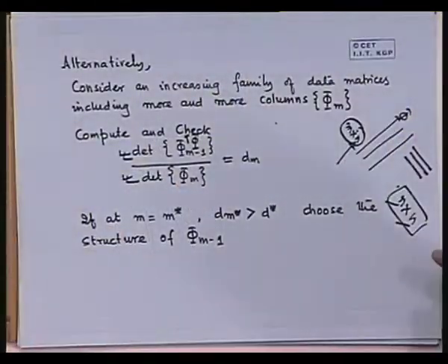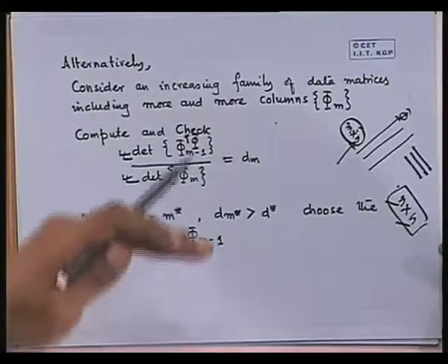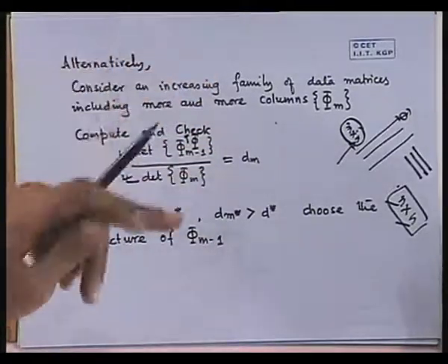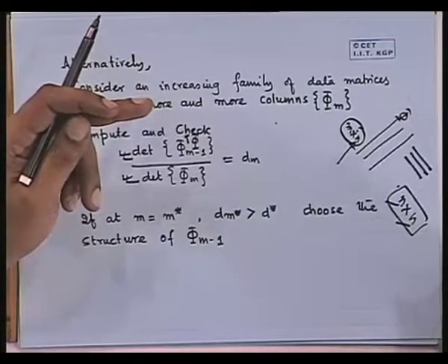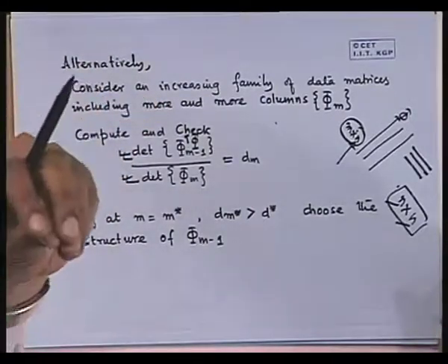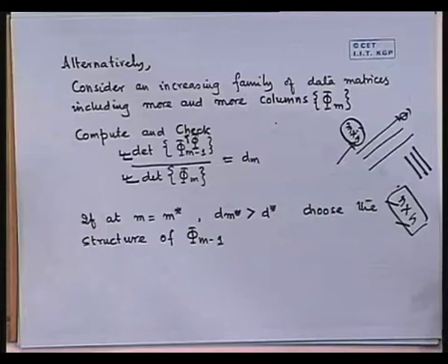So immediately that will show on this ratio. The idea is that you go on increasing the model order, every time compute determinant of phi transpose phi and check when the determinant is falling rather sharply. Stop at that level, don't increase.